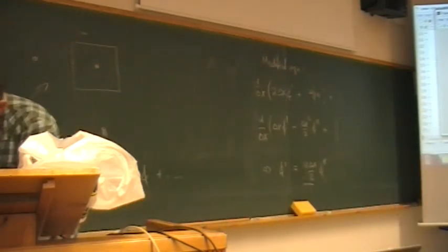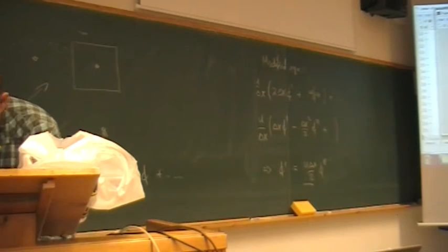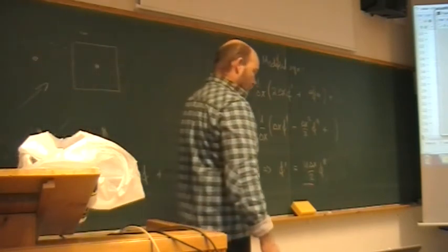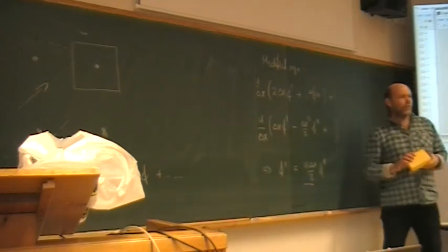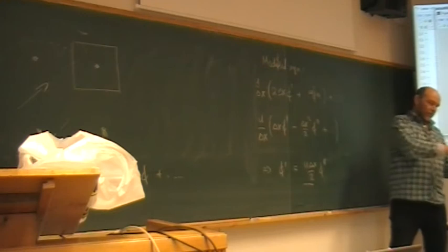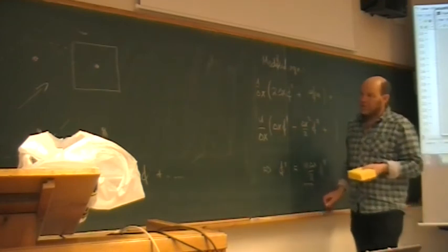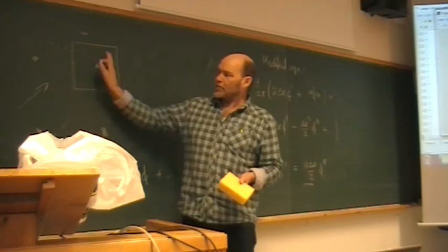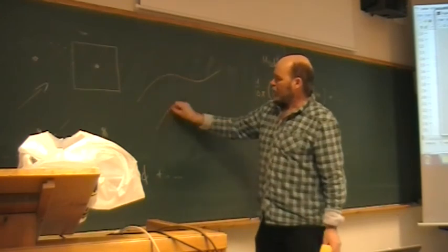We should maybe have a look at... Oh, we can wait. We are going to later on, when we start looking at unstructured mesh systems. There we more easily have an option to create grid lines that are parallel with the flow. So, of course, if this is the flow direction, it would be silly to make such a mesh. You would tilt it 45 degrees. But in a real flow problem, a streamline something like this.